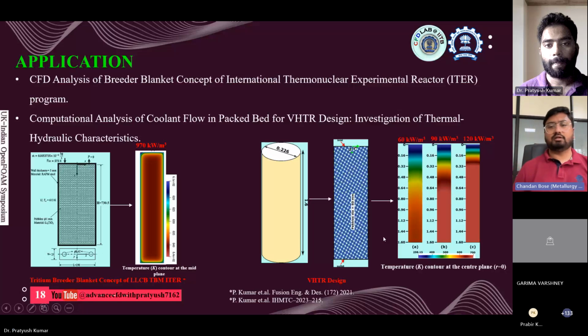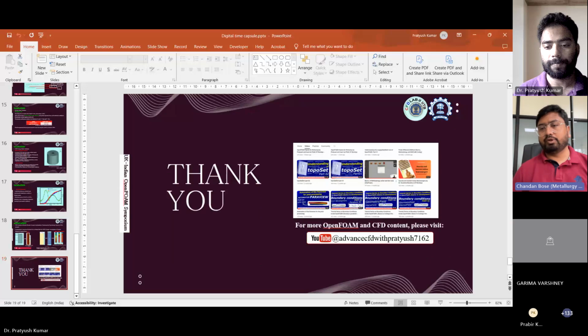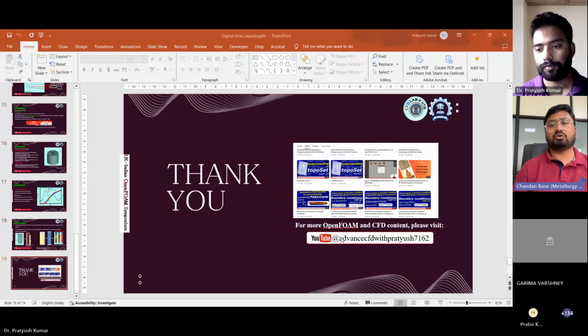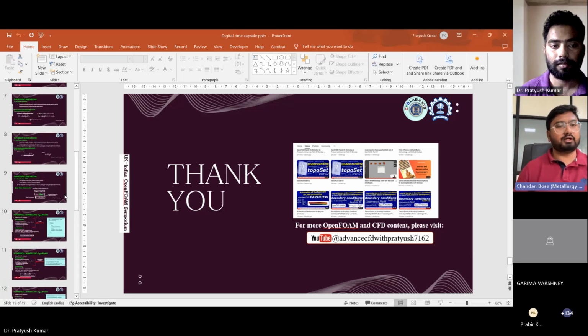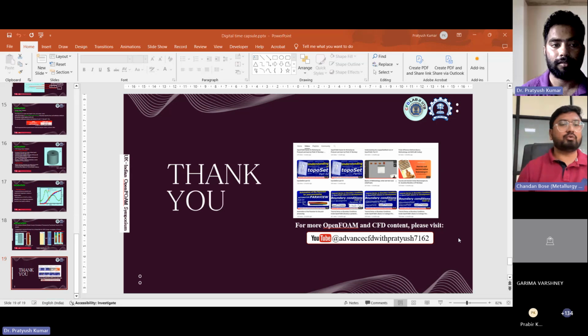Thank you very much. It was a really interesting talk. I request you to see if there are any relevant questions to answer, but I just want to make a comment that the source term that you are adding, in terms of Darcy and Forchheimer coefficients, they are related to the permeability, right? Yes, sir. Because the porosity term should be included in terms of the Brinkman terms, which I think you are not including in the equations.